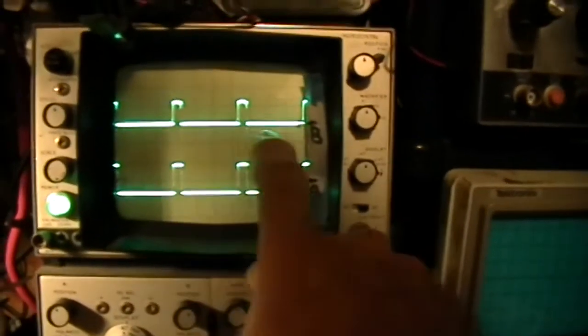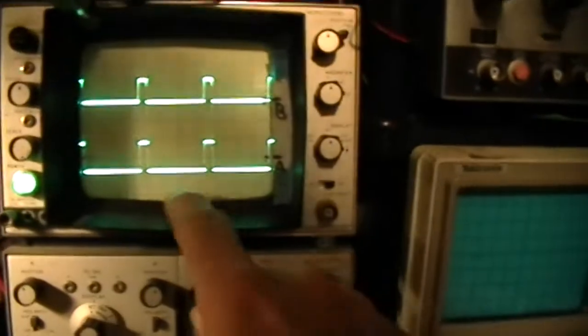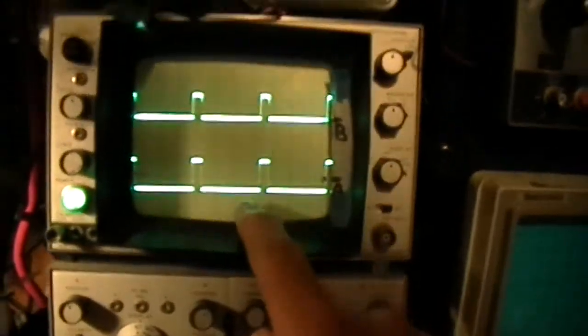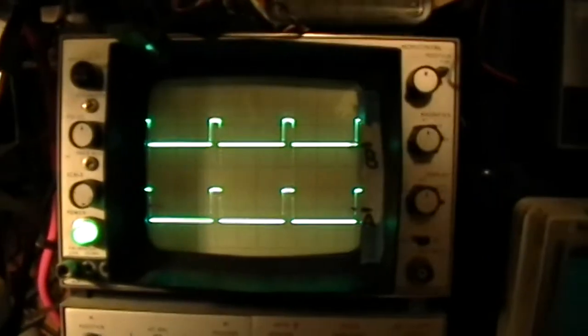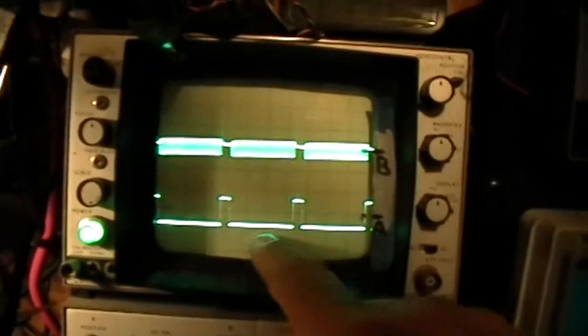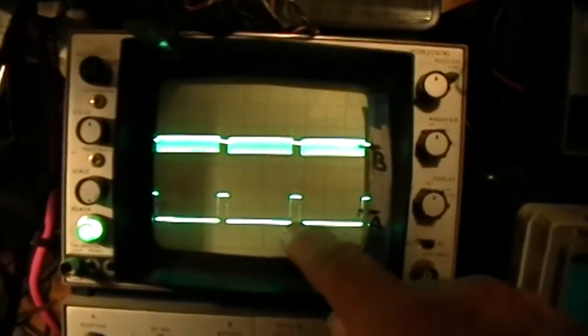We haven't started seeing any oscillations yet because we don't have enough negative voltage yet. So let's add a little bit of negative offset. We put the negative offset on and then lower it a little bit. You don't see it going down here because remember it's clipping at minus 4 volts.